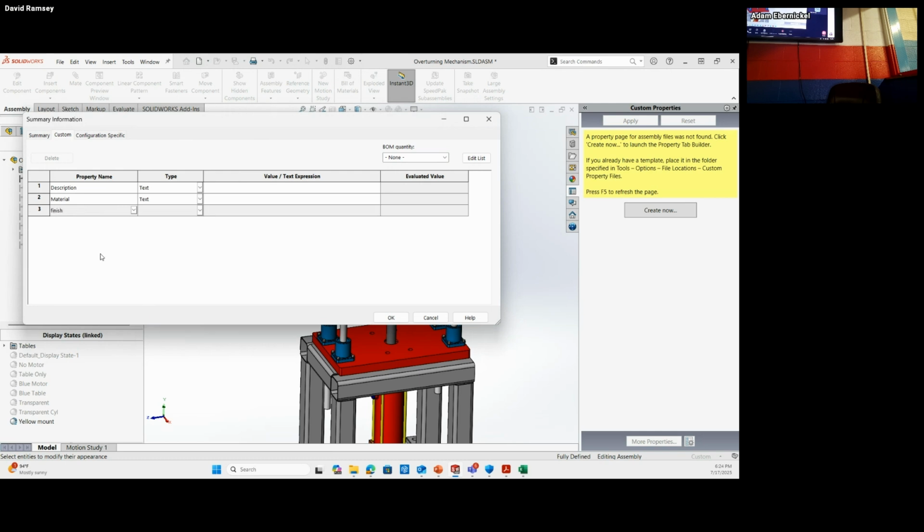Real simple. Recently, I was creating a template, and I have not done it in ages. I was trying to lock down how things are dimensioned, the font size, the arrow types, balloon size, and all that. I saved the sheet format and then saved the template, but it would always revert back to some other default. I couldn't understand what the process was. I've forgotten that. It's been so long since I created one. So when you say you want to control the dimensions or the fonts and all that, does that travel with the sheet or travel with the template?